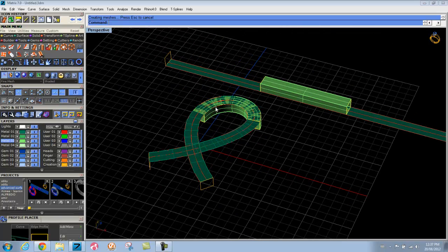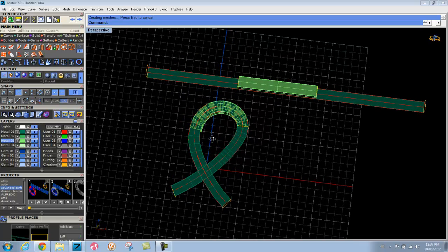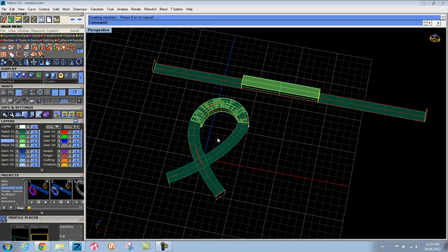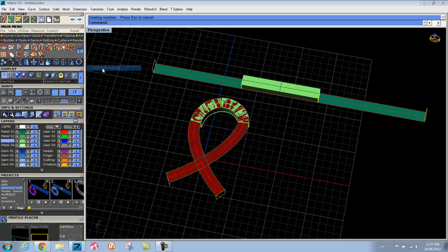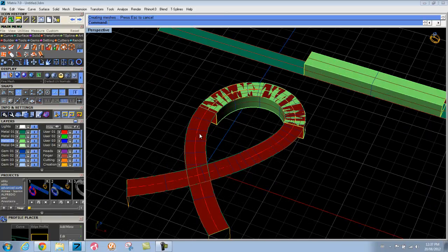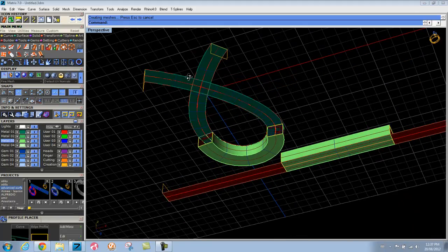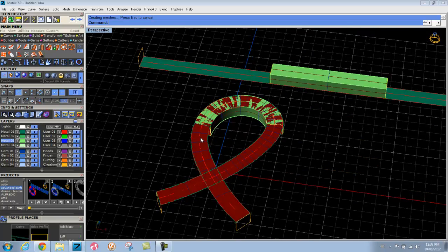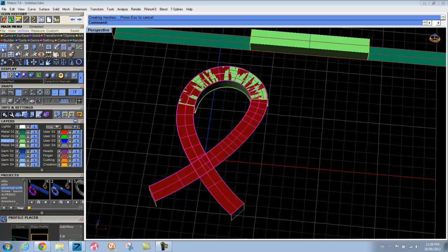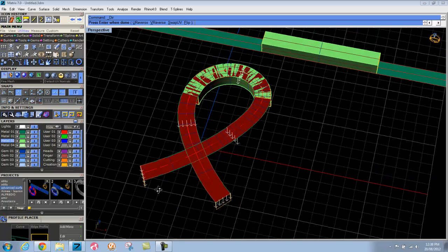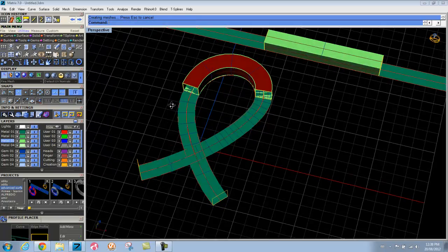Okay, if this is showing up upside down, there's a view shading type that will allow you to look at if the surface is inside out or not. If I right-click on the name of the viewport, there's one called Detect UV Normals. The red color means that that's the inside, so in this case, this is flipped upside down. That should be that color facing up. I can flip a color by selecting that surface, going to Utilities, and changing the direction. So to flip them, I'll select Flip right here and press Enter.